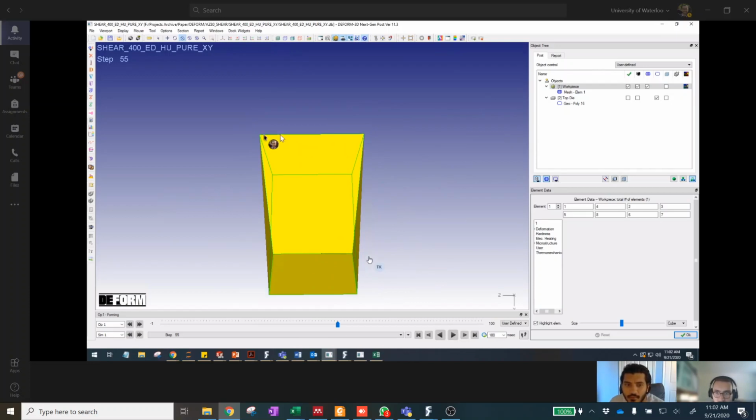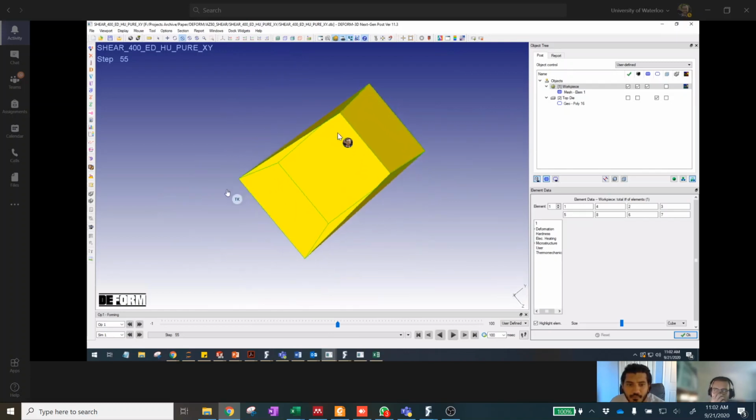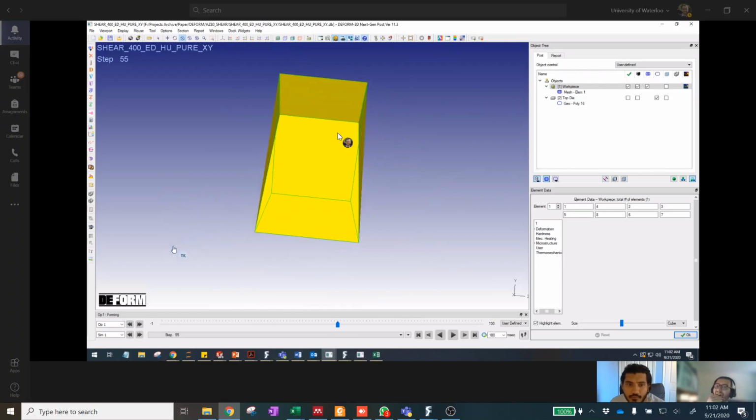Actually, that's the problem: these are the two nodes that you've constrained. Why is it over constrained? This is the other thing that I noticed. If I were to set Z constraints to these faces, I guess I would only constrain one face. So you need one node totally constrained for translation, and then the other one, I might have missed that. So I need to constrain only this corner node here in the z-axis, only one of them, yes.